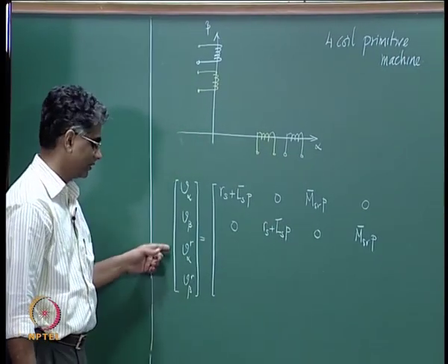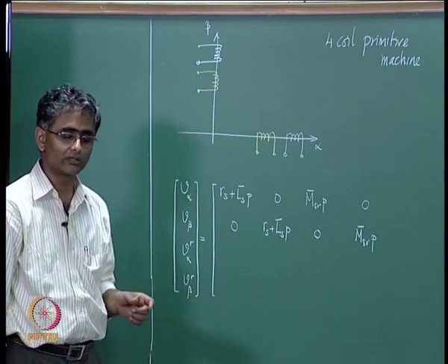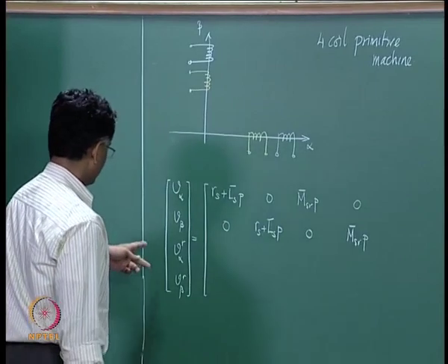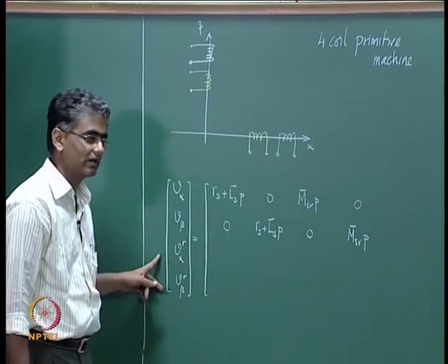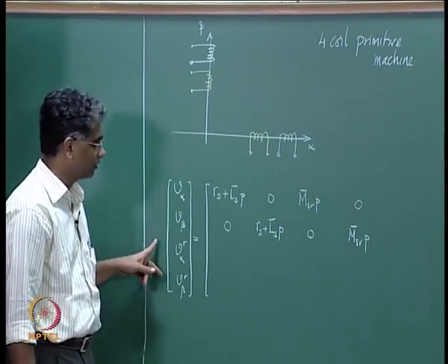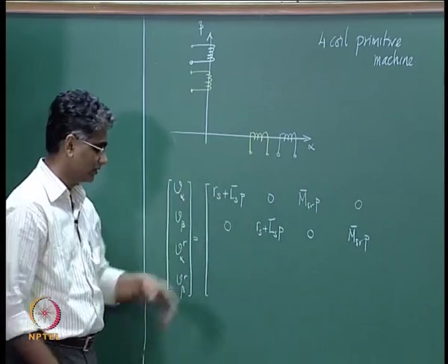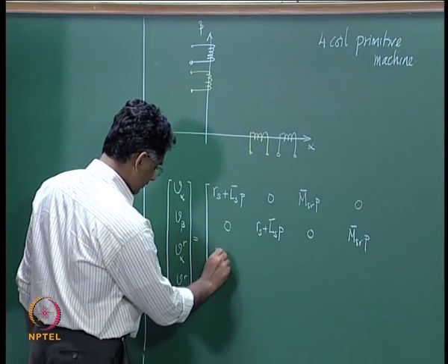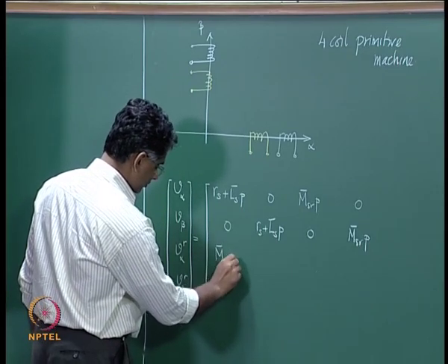These two equations are going to be for fictitious coils which were actually rotating, but now you have considered them in the stator attached reference frame, therefore they are pseudo stationary fictitious coils, and therefore you will have speed EMF terms.